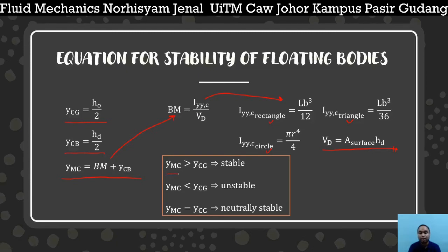If your YMC is higher than YCG, you will have a stable body. If your YMC is lower than YCG, you will have an unstable body. And if your YMC is equal to YCG, you will have a neutrally stable body.